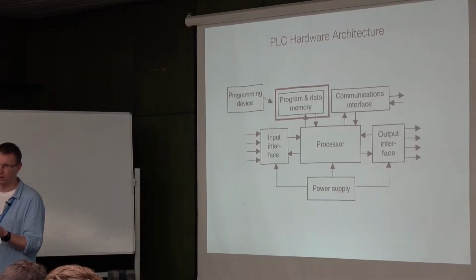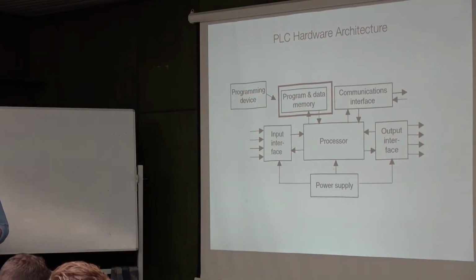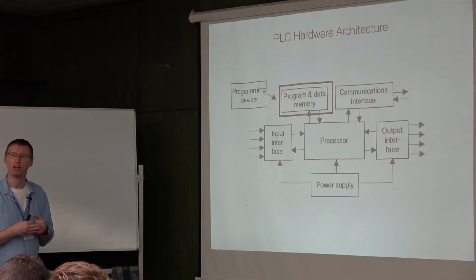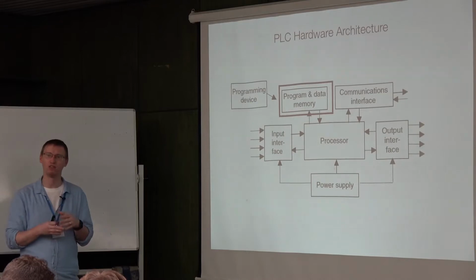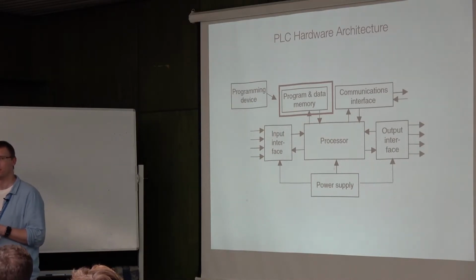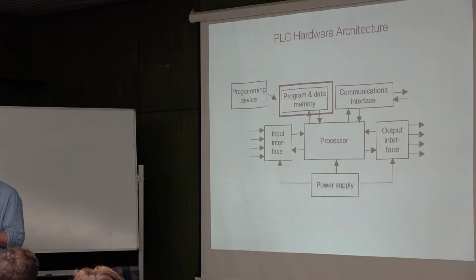Then people realized they are a very versatile type of hardware, so they added the capability to process also floating point math. And for that, you need to start working with these kinds of variables. So there are types of blocks which take not logical inputs, but numbers. Or it can be some internal variable of your control algorithm, for instance.